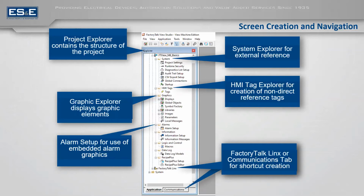The next primary folder is your HMI tags. So there are two different ways you can address PLC. You can create HMI tags, which allows you to import and export. So it's kind of a good feature if you want to bulk edit your content. The other option is for direct referencing. So direct referencing will not show up in your HMI tags, but on the individual graphics. So inside the Graphic Explorer itself, you would open up a display.